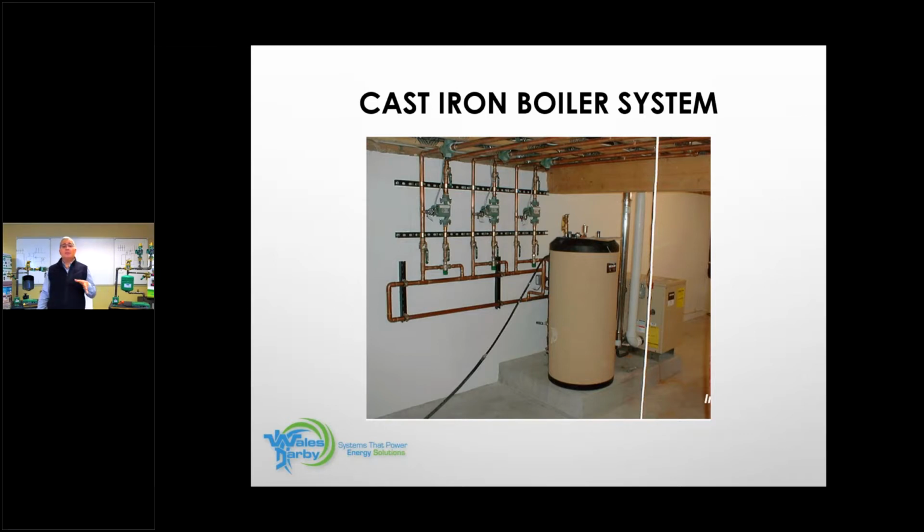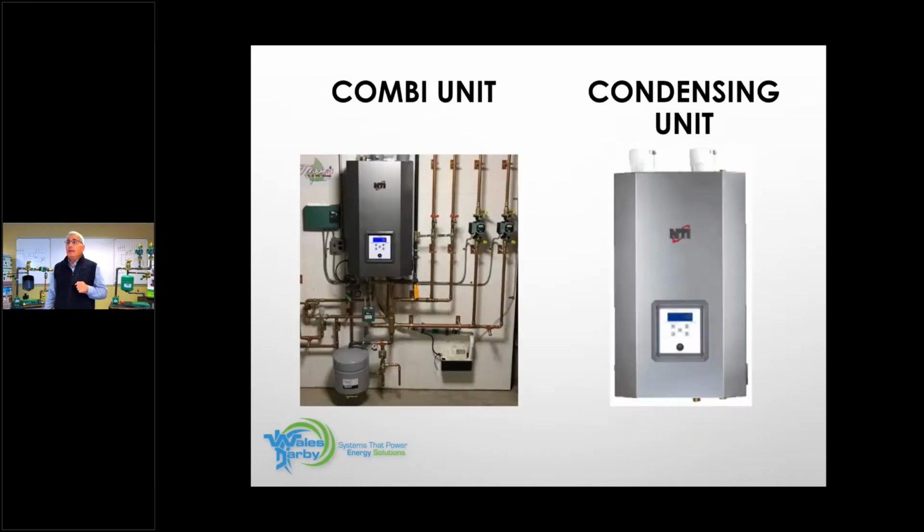But the boiler only knows one thing: to fire to its limit. If we go to condensing, we want to take advantage of that. We want to run the lowest water temperatures we can, and we want the boiler to run off of outdoor reset. Again, the NTI TRX boiler has the ability to run off of internet weather. So that gives you an advantage of not having to crawl into the crawl space to get to the north side of the building, get your wire out there and get your sensor out there, okay? And it's accurate. It's very accurate. It's accurate for right where they live. All right, so that's another option there.